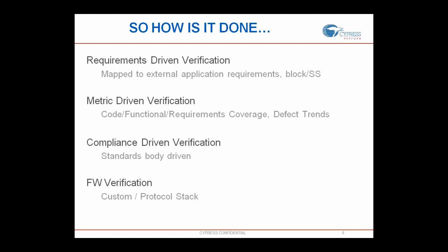Bluetooth, there is a SIG, the special interest group, which runs these tests at the Bluetooth qualified test facility. So we have to take our silicon to these standards bodies, and they will run through a set of test cases in certain ways, and you have to pass that. So one has to consider this upfront during the planning of the verification plan, to include at least a subset of tests, or a test which could be simulated in verification. If it is not possible in verification,